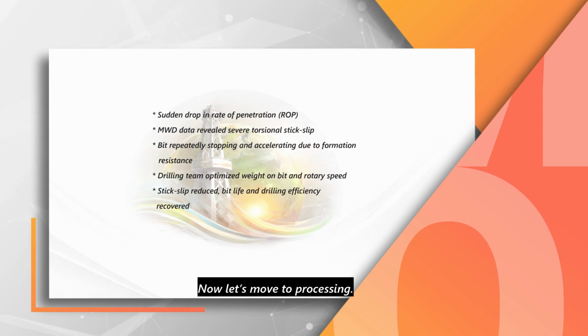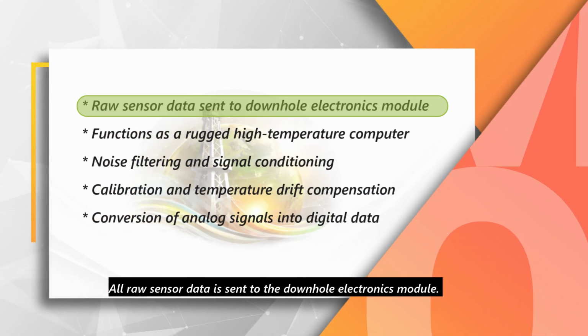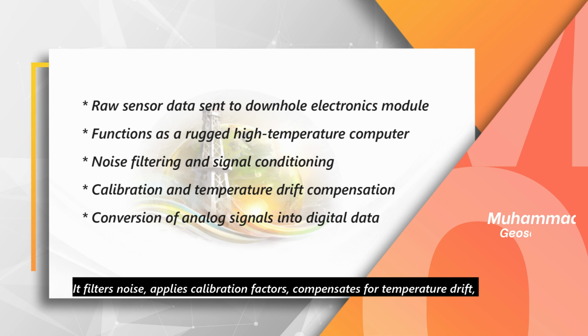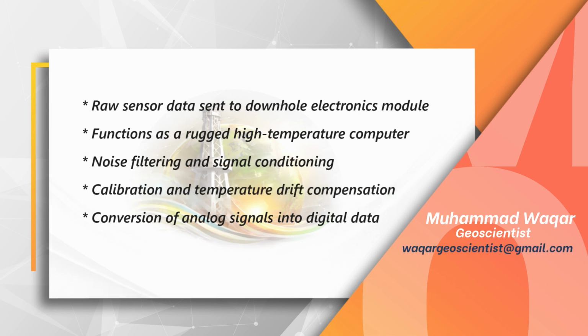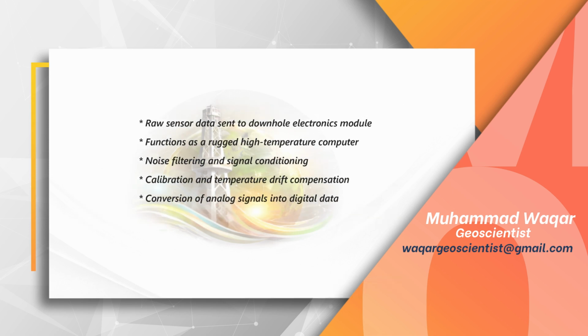Now, let's move to processing. All raw sensor data is sent to the downhole electronic module. This module acts as a ruggedized high-temperature computer. It filters noise, applies calibration factors, compensates for temperature drift, and converts analog signals into digital form.